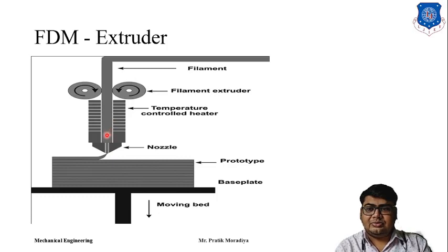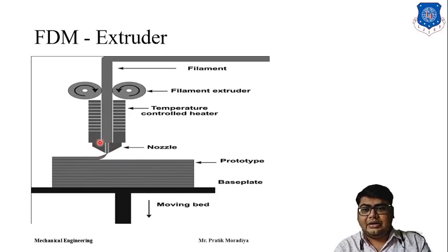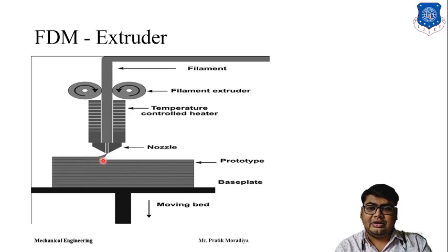As the filament gets melted, the filament extruder will feed the filament, and the filament will itself force the liquid out of the nozzle. The part can be built layer by layer. You can add this layer, and it will start to cool as it comes into the atmosphere, and as it cools you get the new layers of solid.